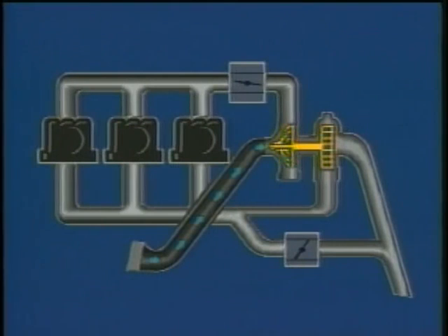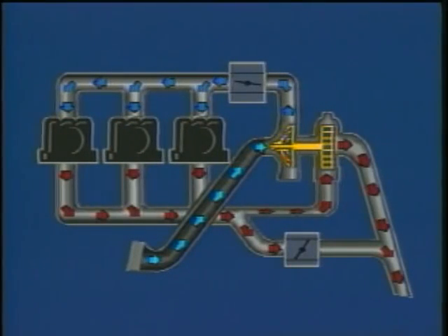As air enters the intake, it passes through a compressor where it is compressed by the centrifugal force created by the impeller blades. The compressed air is then routed from the ring surrounding the impeller through the throttle body to the cylinder. The compressor is driven by a turbine which is propelled by the engine's exhaust.